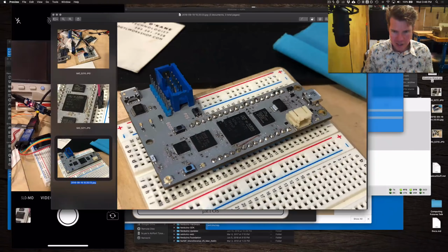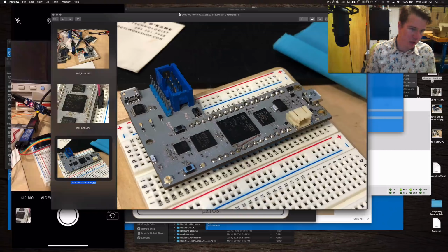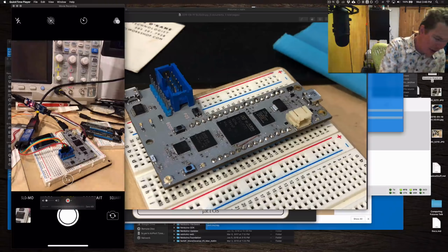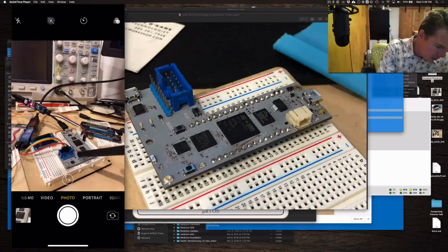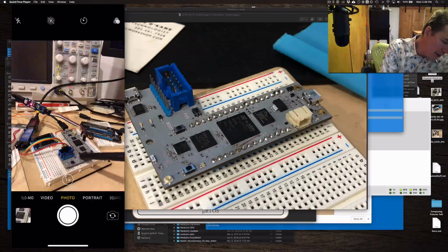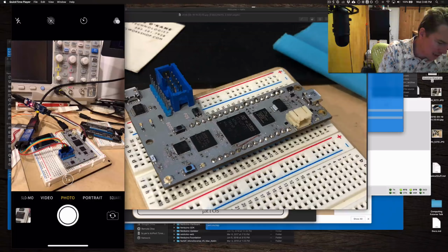It's really easy for the NetX to output debug information over serial, and ordinarily we'd just plug in a USB. But the mistake we made was that we swapped the RX and the TX lines, so effectively we made this section of the board completely useless.